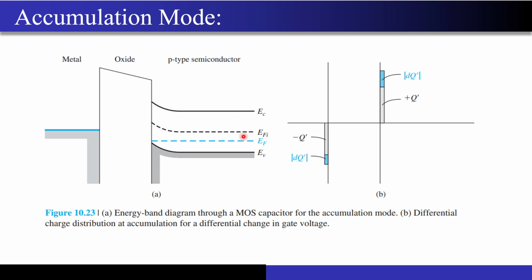Now we have studied the CV characteristics, and what did we say? What is this capacitance actually? For any particular small change in the voltage that I will apply across the metal, I will get some differential charge addition over here, right? So on top of this charge density, this dq dash got added over here, and correspondingly the positive charge got added just to balance it out, right?